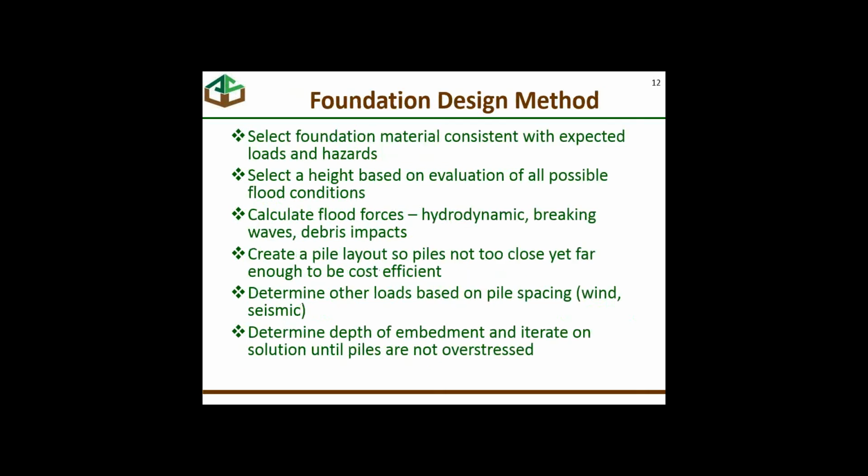The foundation method that I've used most often and that I see lots of other practitioners use is a pretty cryptic method. Let me just go through it kind of quickly. We need to pick a foundation material that's consistent with what we think the loads are and what the hazards are that we've identified. We obviously have to select a height based on the evaluation of all the possible flood conditions. Now, that height might be driven to some extent by a height restriction in the community, or it might be driven by an owner wanting to make sure that their building is well protected from a flood.